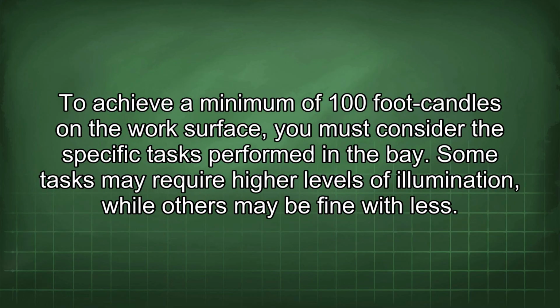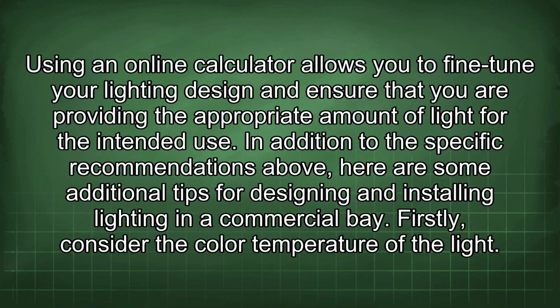To achieve a minimum of 100-foot candles on the work surface, you must consider the specific tasks performed in the bay. Some tasks may require higher levels of illumination, while others may be fine with less. Using an online calculator allows you to fine-tune your lighting design and ensure that you are providing the appropriate amount of light for the intended use.